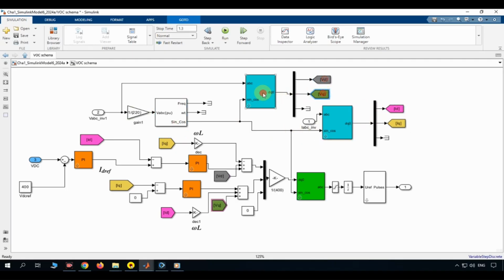At the same time, the grid voltage is transformed from the three-phase ABC frame into the rotating DQ0 frame. This transformation uses the frequency and phase angle extracted from the grid voltage itself, acting as a virtual phase locked loop. This step allows the controller to represent grid quantities as steady values instead of sinusoidal waveforms, which makes accurate regulation possible. The measured grid current is transformed into the same DQ0 frame, producing the direct axis current and the quadrature axis current, labeled ID and IQ.